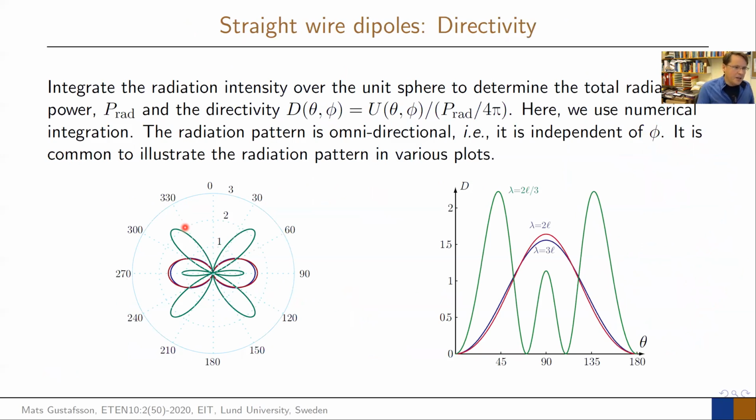And this is again the same way of plotting it. So we can plot the directivity here. You can see here, this is the max. It's easy to see at 135 degrees. That means it is this direction. So when you look at these polar plots and the Cartesian plots, you can compare how they radiate, and you need to be able to understand what these plots actually depict in these cases.